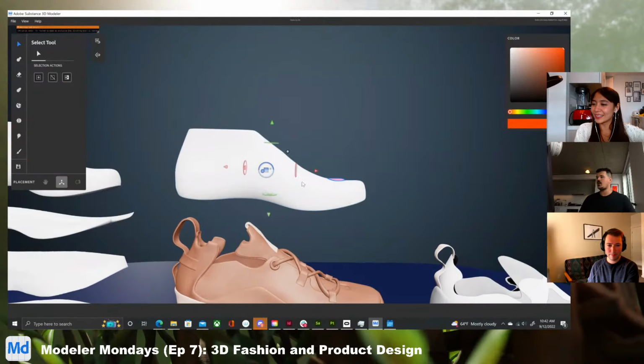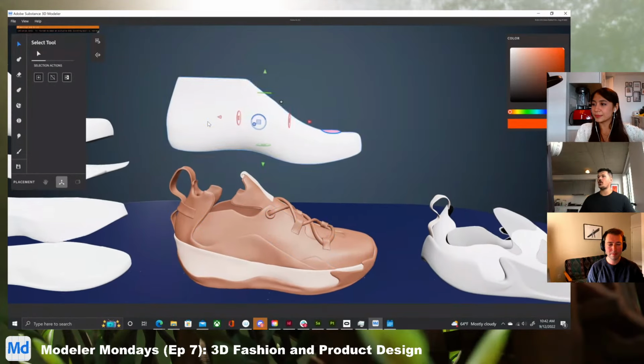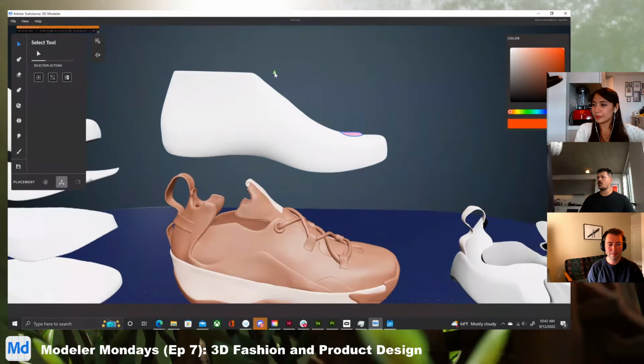What I was saying before is it's really hard to get these thin surfaces with just the basic clay brush. But knowing that I can boolean it, I know these two shapes are 1-to-1, except one's a little bit smaller because it's tucked away in here since I sized it down. So I'm going to throw my headset back on, and wherever I want stuff to reveal, I'm just going to pull the.